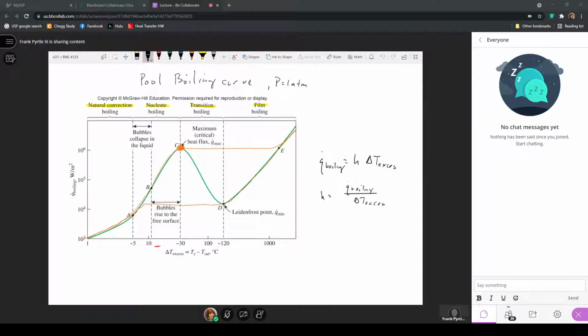In boiling heat transfer, the expressions of the heat flux are specifically given because different fluids have different temperatures at which, let's say, nucleate boiling might start to occur, or the film boiling regime might actually exist. And the fluid properties have so much to do with the consideration of when boiling starts, such that vapor bubbles are formed on that solid surface where the liquid is changing phase.